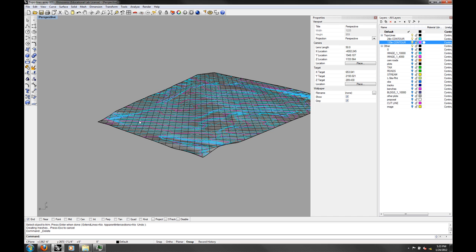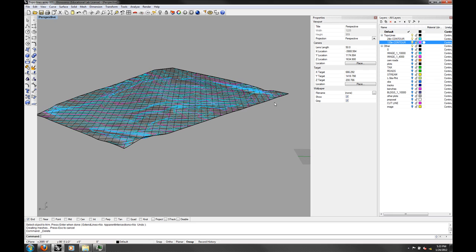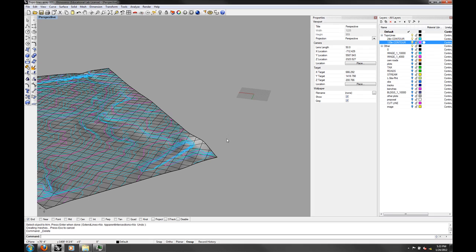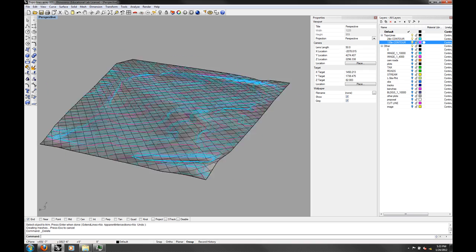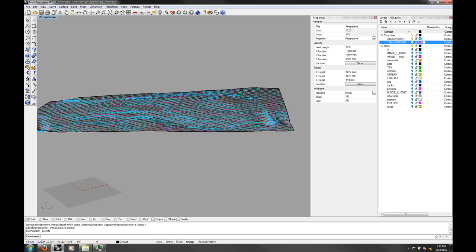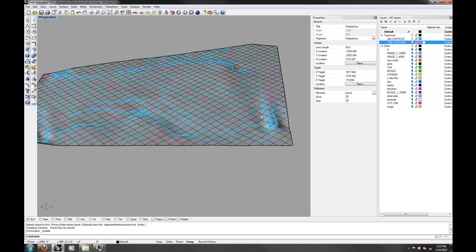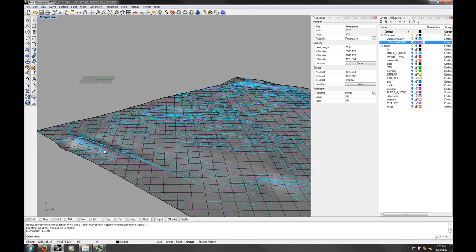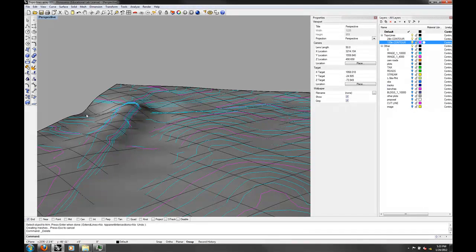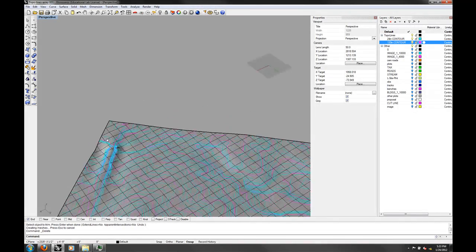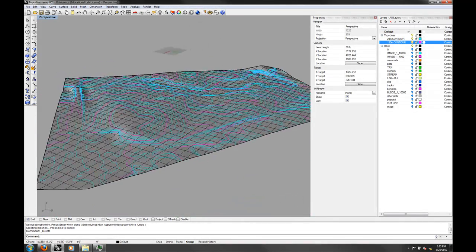If you're interested in accuracy, I can show you a more precise method. What we can do though is that if you have a contour that happens to run through this piece, you can just edit that piece of it out when you're in AutoCAD or when you're in Illustrator. Most of the site, I've checked it, actually patches pretty well. This piece right here is another kind of thing too. Mostly at the edges where there's not enough data, it creates some funky things. So just be aware of it, and you can edit it.